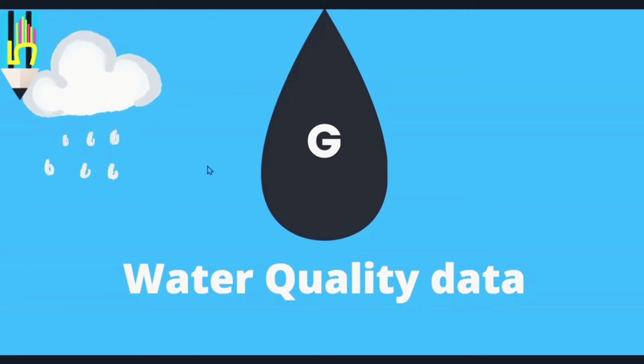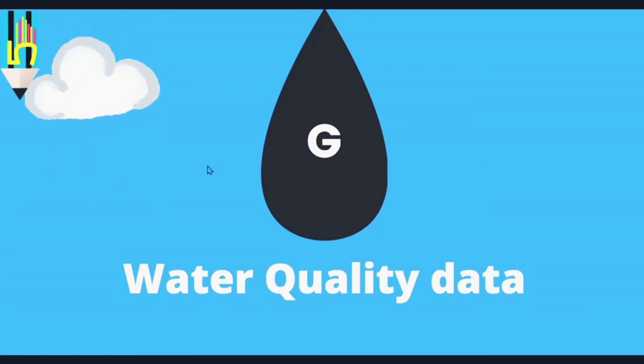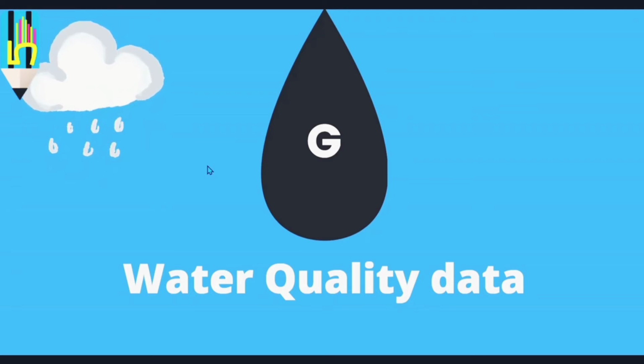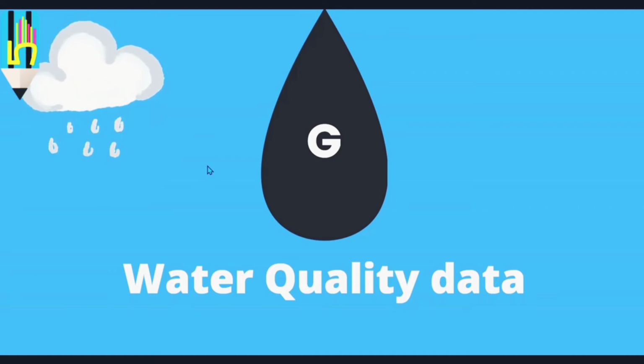For the pro forma of water quality data, like the format which you need to collect this data, how you can get that format will be discussed at the end of the video. And this is very important because in cases of surface water, you need to have a very clear picture of what quality of water is coming. Based on that, you will either give a WTP, that is water treatment plant, or, if the water is clean enough, you will give some filtration followed by chlorination and then supply the water. So this is very important.